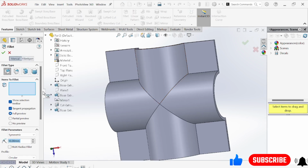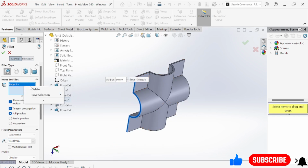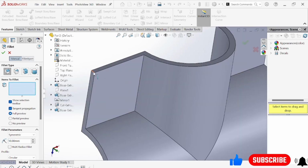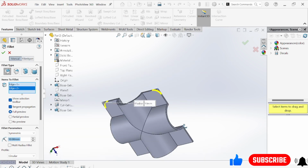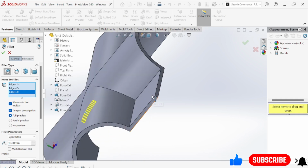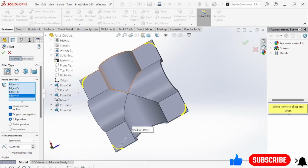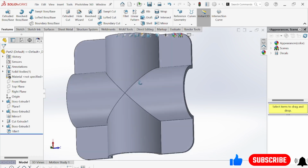So go here, make fillet, select this corner, not face actually, for face got selected, simply this one, simply select this one, select this one, and select this one, and make this one okay. Now here you see this is our upper part. Actually this is a plastic part.